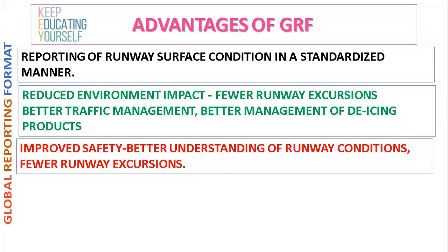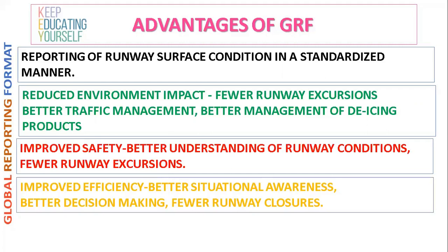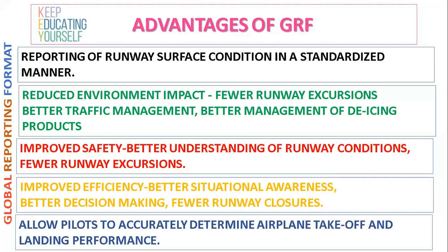As we will be using the global reporting format, we will have a better understanding of runway conditions. Thus, it will result in fewer runway excursions. Improved efficiency, better situational awareness by aircraft operational personnel. It will help pilots in decision making, thus fewer runway closures. It will allow pilots to accurately determine airplane takeoff and landing performance.